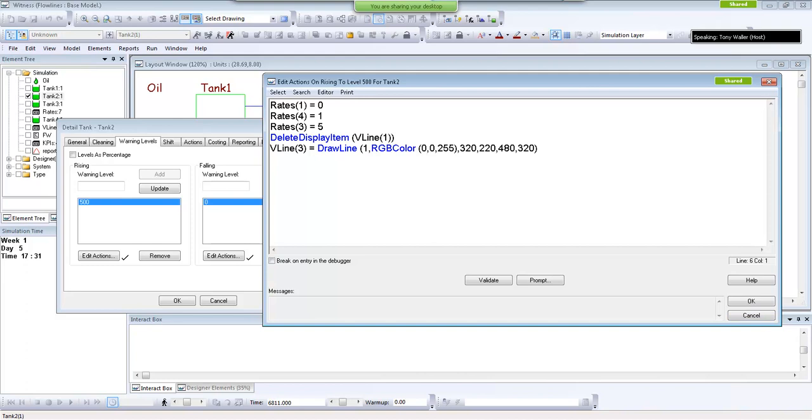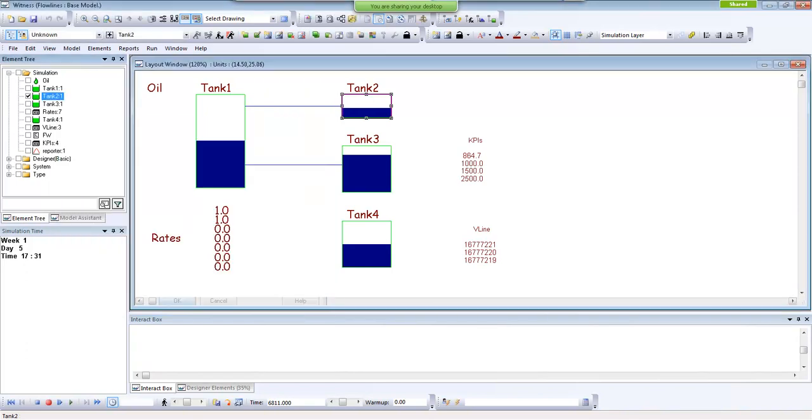The parameters for drawing a line are the coordinates, which are the last 4, but the second one there is the color, and that's RGB color. That's another function in Witness, which sets it in terms of red, green, and blue function parameters. You could just put a single number in there, but using the RGB color function means that you have much more certainty over which color you're getting if you're used to working in those RGB parameters. So it is those functions which are drawing those lines.